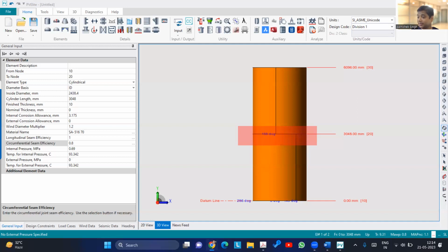The second question, how do we come to know the number of heating cycles? Okay, very good question. Anybody can tell me how many cycles I need to have based on PWHT as per code required? Guys, how many cycles? Cycle means what exactly? Cycle means the holding time, right? Heating and then holding that vessel at that temperature.